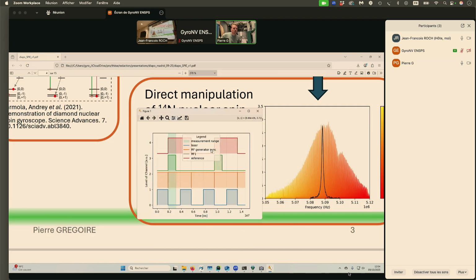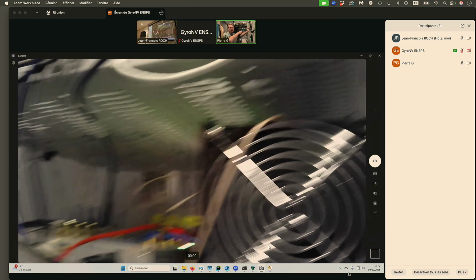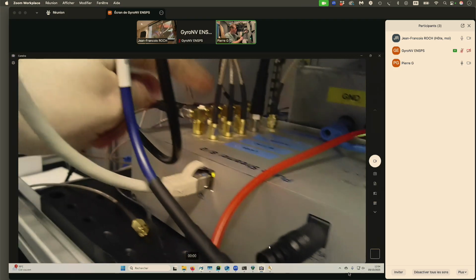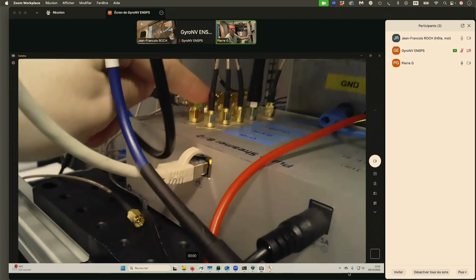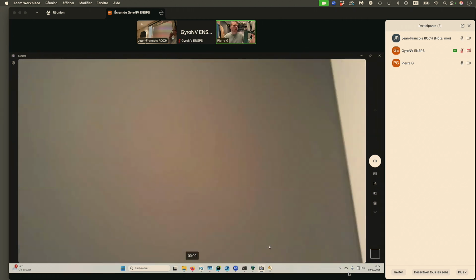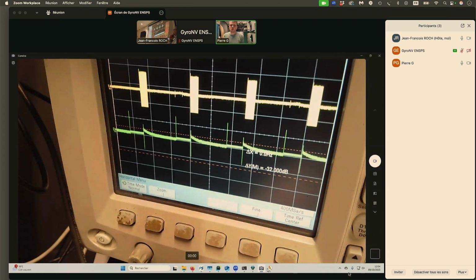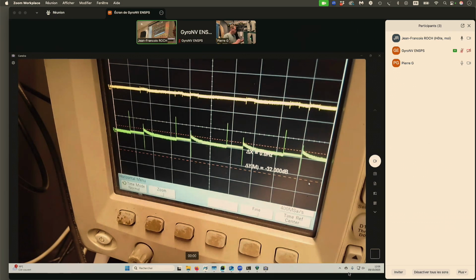this is the sequence of pulses I will send to this device here, and this device will send those impulsions through here, and those are used to open and close switches, RF switches here, and you'll see the result on the oscilloscope that's here. Okay, so these are pulses of the radio frequency drive at 5 megahertz, and using a Mini-Circuits driver, we can shape them as pulses. Okay.